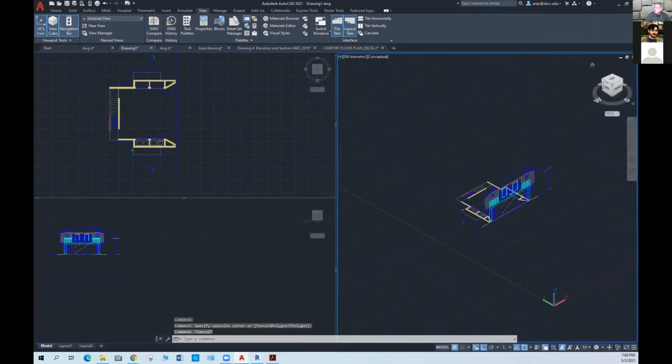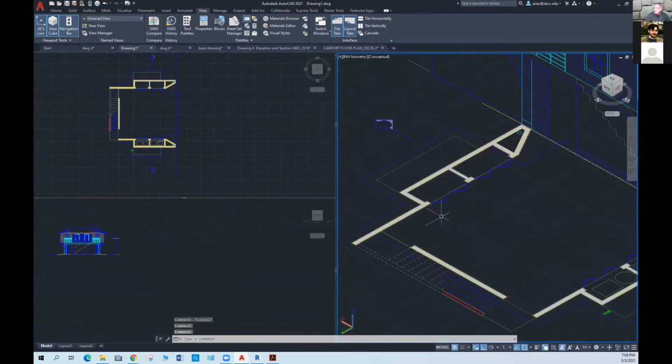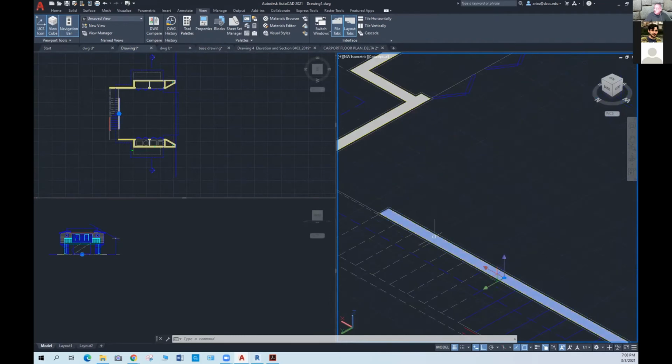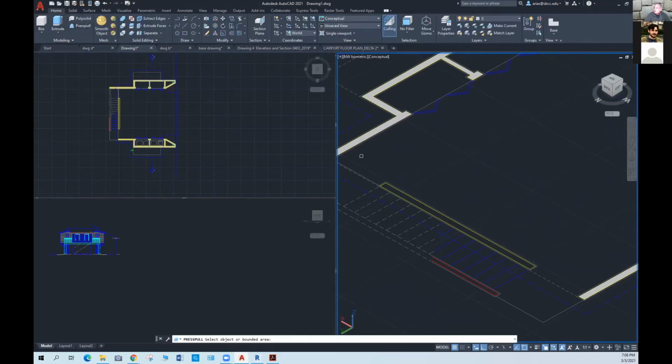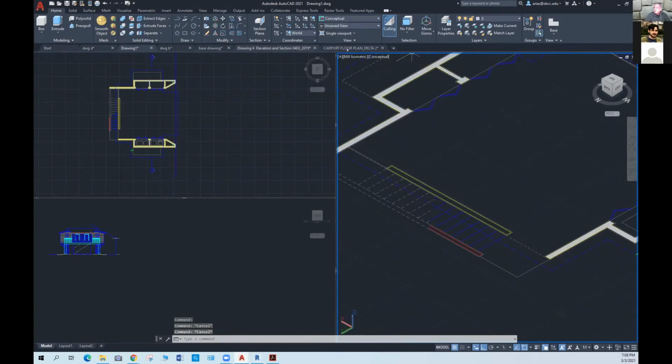For example, if I go here and I say, okay, I want to create a particular shape, but maybe I want to create this wall, right? And so I'm going to do a press pull. Remember, press pull, click inside that. And to create press pull, you really need to make sure that you know where your UCS is.